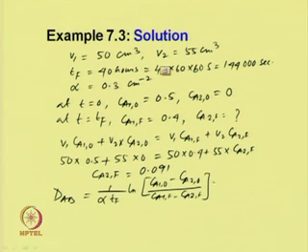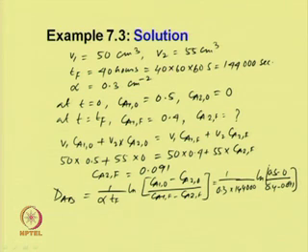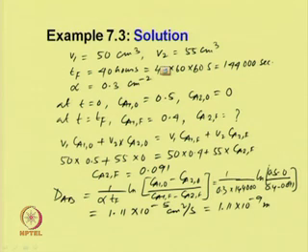Now, putting the value, 1 by 0.3 into 14400 seconds ln of (0.5 minus 0) divided by (0.4 minus 0.091). So, this will give 1.11 into 10 to the power minus 5 centimeter square per second, which is equal to 1.11 into 10 to the power minus 9 meter square per second.